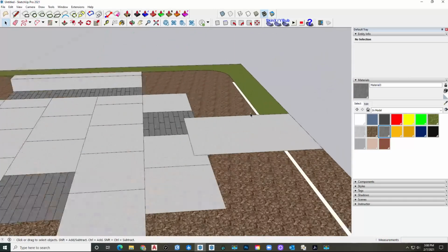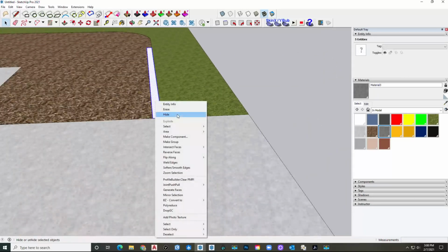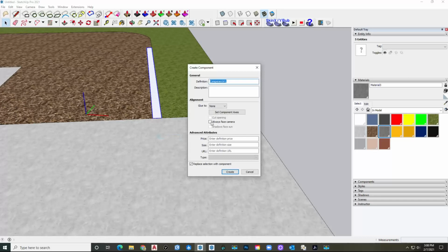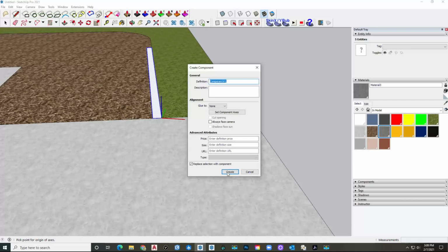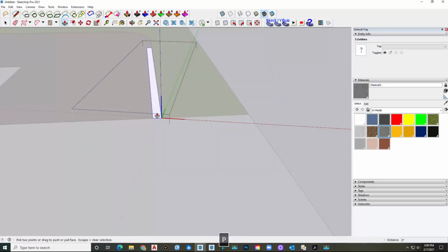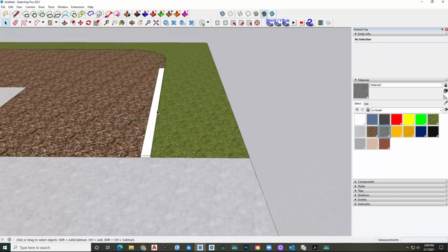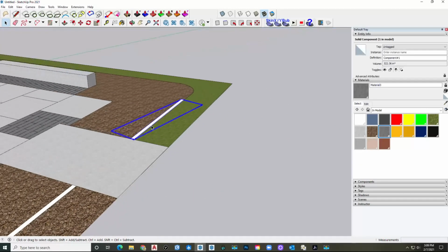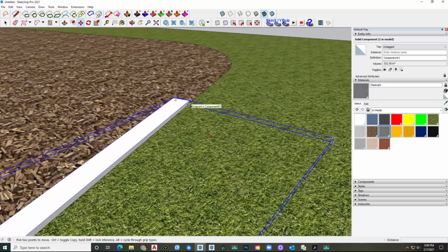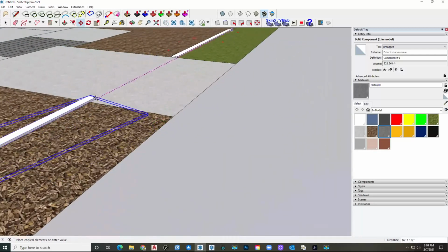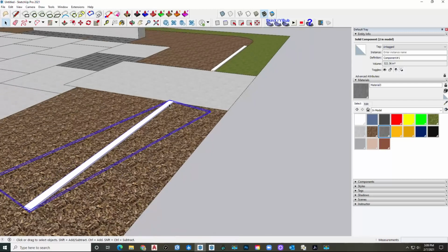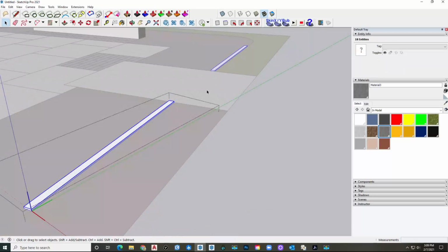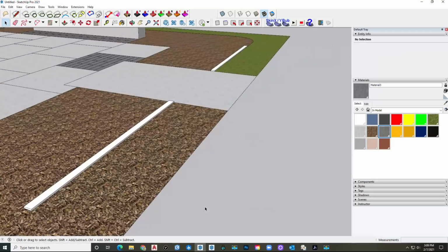That's good. Now these are going to be railroad ties, so I'm actually going to make this into a component. Component axis here. Say create. Double click. This one does not need the face camera because this is actually a real piece of static 3D object that we're making. So I'm going to raise that a little bit, and then I'm going to copy. I'm going to click here, and then M for move. And when I hold Control, it allows me to copy it. It turns into a plus. So I hold it and let go, and it allows me to copy that object. I'm going to bring it over. And again, the benefit of having a component is that when I make one change, it changes the other thing.